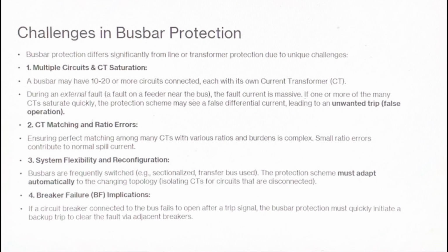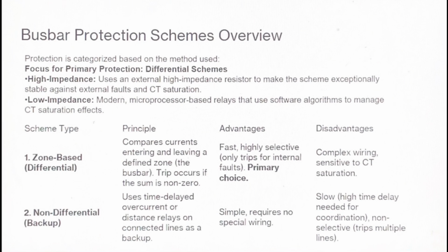Finally, we must always consider breaker failure. If the bus bar protection sends a trip signal and one circuit breaker fails to open, we need a rapid backup plan, which we address with breaker failure protection, or BFP. Next slide is about the bus bar protection schemes overview.